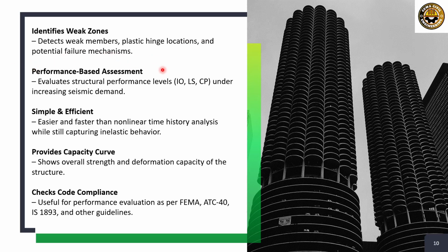Second is performance-based assessment. As I said in the previous lectures, performance-based design is incorporated using pushover analysis. We see different performance levels, that is, what kind of performance the building is giving. So it evaluates structural performance levels, immediate occupancy, life safety, and collapse prevention under increasing seismic demand.